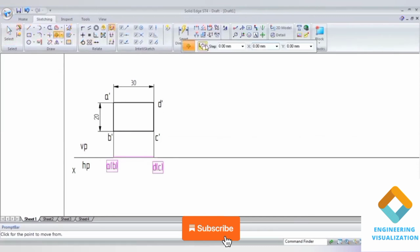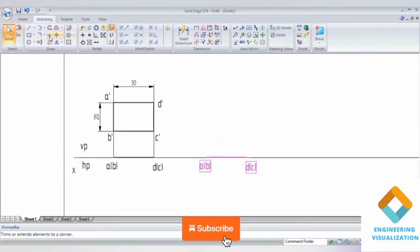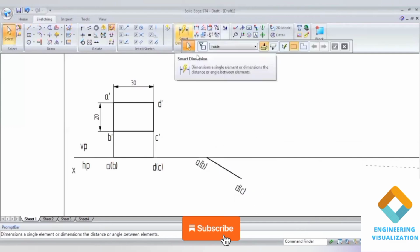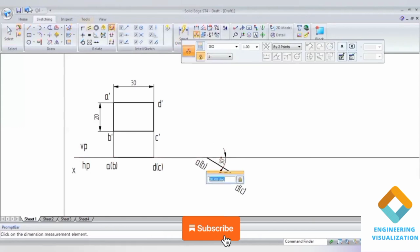Select the top view, go to the move command, create a copy of it and slide along the line, and now we can give the inclinations. So inclination to the VP. Here I'll give the angle of inclination 30 degrees. Inclination below the XY line means we have to give minus 30.